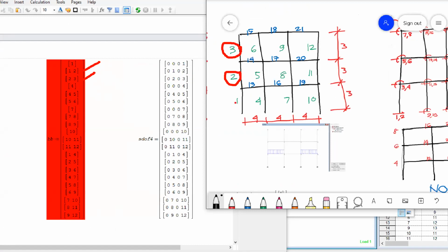And we'll go back to the column on the ground, number 4 here, member 4. We only need the fourth element. What's the code for that? It's 12 here. And the location is on the fourth element on our S matrix. Okay, so on and so forth.